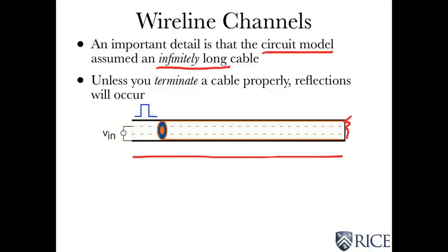So, suppose you have a physical situation where you have some length of coax and you just cut the end off and you leave it open. Well, at this point, that current has to be 0 because it can't flow between the two conductors. That's what cutting it means.